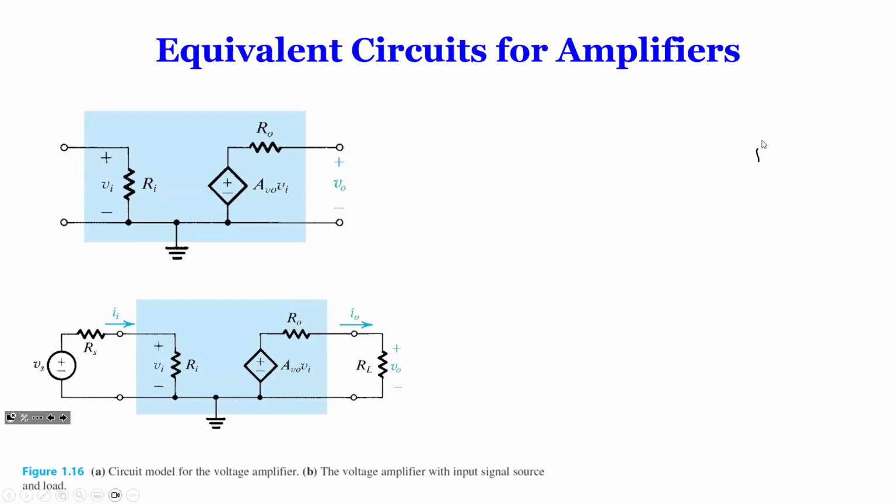So what are you amplifying? Are you amplifying Vs or are you amplifying Vi by looking at the circuit? Well, you see here, actually, this voltage gain is multiplied by Vi. So we're actually only amplifying this signal, not this signal. Okay, you say, fine, what's the difference? Well, the difference is quite big depending on what your internal resistance is. Let's say your source resistance is 1 ohm, and this is 1 kilo ohm. What happens to your amplification?